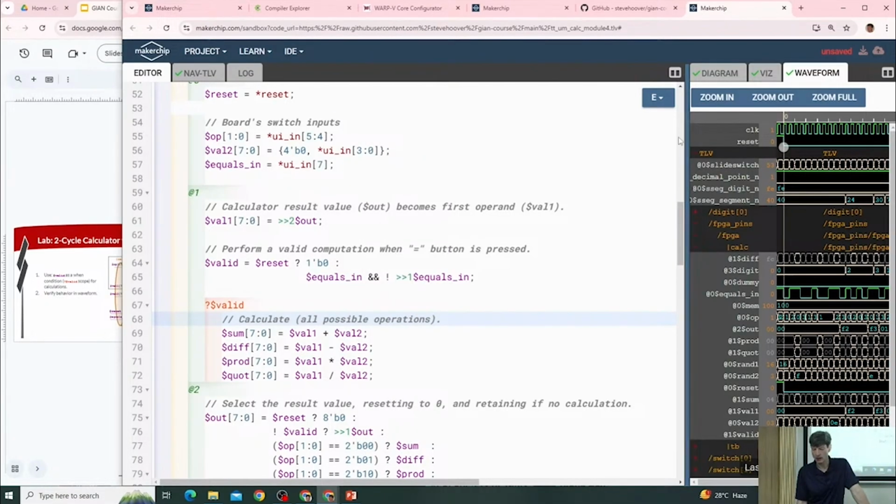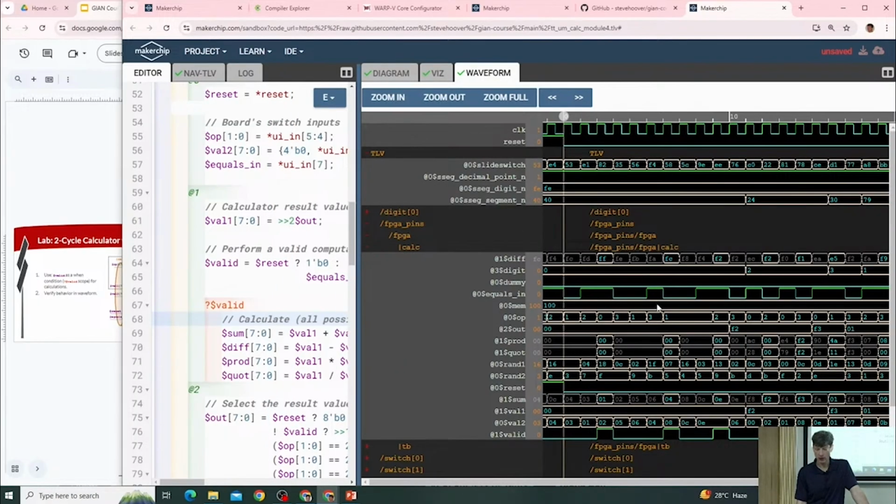Yeah, the grayed out signals are under a when condition that is deasserted. You will see values there. I mean, you do see numbers in gray. Again, Verilator is a two-state simulator, so we're not modeling don't cares in the simulation. They do have values. You can see the values, but you know that they shouldn't matter.